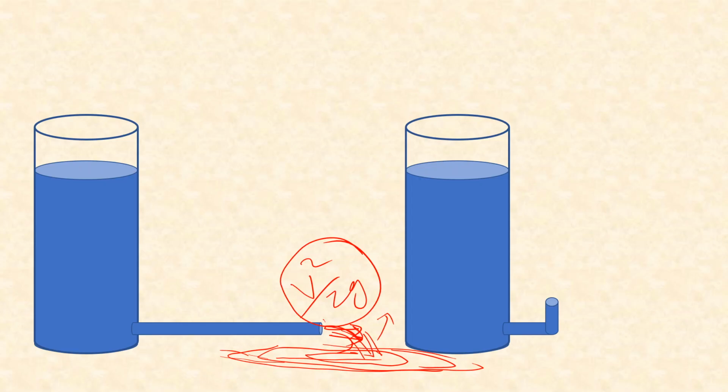Again, if we consider something where it is flowing up, then it will flow up to almost this level, almost, because while flowing some head is already lost because of friction inside this pipe, and also due to friction with the atmosphere, so it will not exactly reach this level, maybe slightly here.